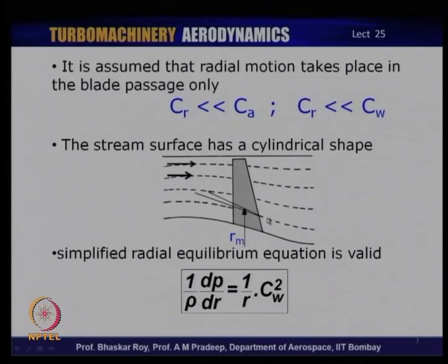However, near the hubs it is entirely possible that it would acquire a certain amount of radial component. So, the designers by design quite often try to balance the forces, the statics and the dynamics, and as a result try to minimize the actual radial flow component to the minimum value.